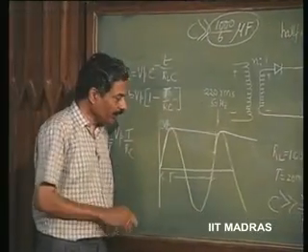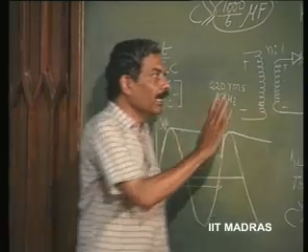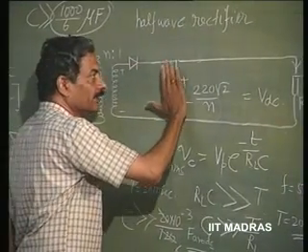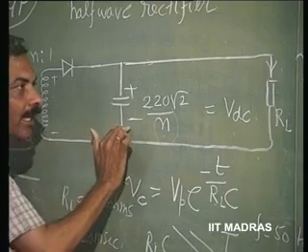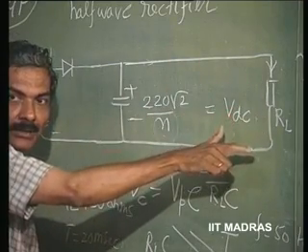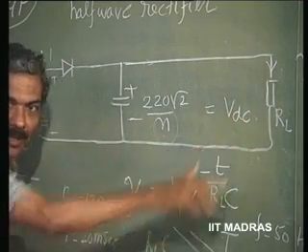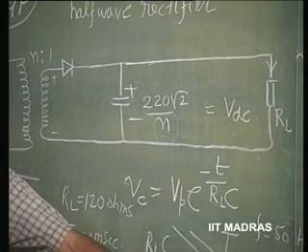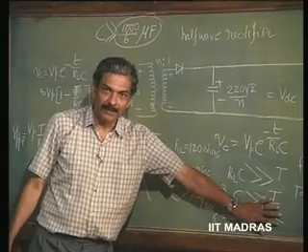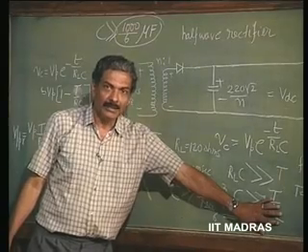It is not done that way. What is done is, I would like to convert it into a DC, then put a capacitor, which does the peak detection. Then I would like to investigate what happens when a load is connected across it and how the discharge can be minimized. That will give us the equation for what to select as capacitor value in order to minimize the discharge.